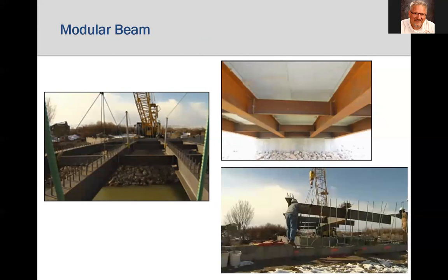The new bridge was designed with 4 longitudinal weathering steel beams. The beams were prefabricated in modular pairs at Wheeler and shipped to the site for quick erection. Simple bolted diaphragms connected the beam pairs after they were set on the abutments. The concrete deck was cast in place and a crash-tested prefabricated steel railing finished the bridge. This video shows the erection of those modular steel units.